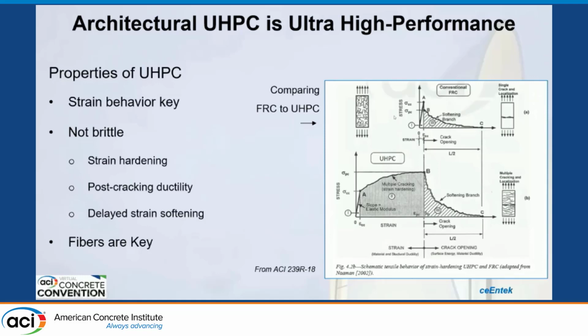If you have a conventional fiber reinforced concrete such as GFRC, or even a high fiber content traditional concrete, you get this conventional situation with your tensile behavior. It will take the strain up to a certain point, point A, and then you have a very rapid softening reaction.